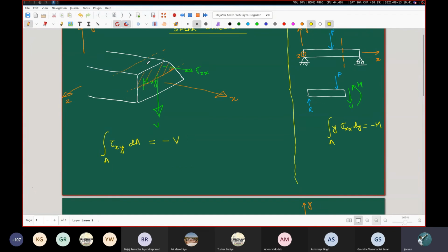The only force that it may be experiencing is in the transverse direction, like we studied in our bending moment chapter. There may be some loading on this thing in the vertically downward or vertically upward direction, but there are no forces along this surface. Because there are no forces along that surface, there are no shear stresses on the top surface. So the top surface is, in physical reality, free from any shear stress.